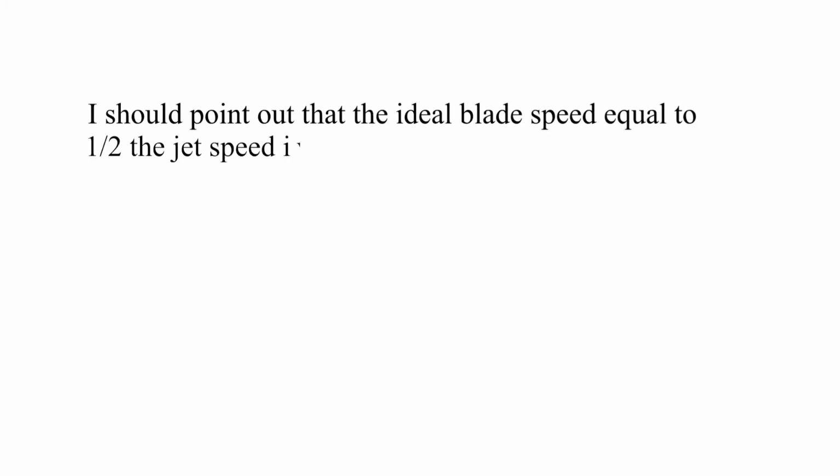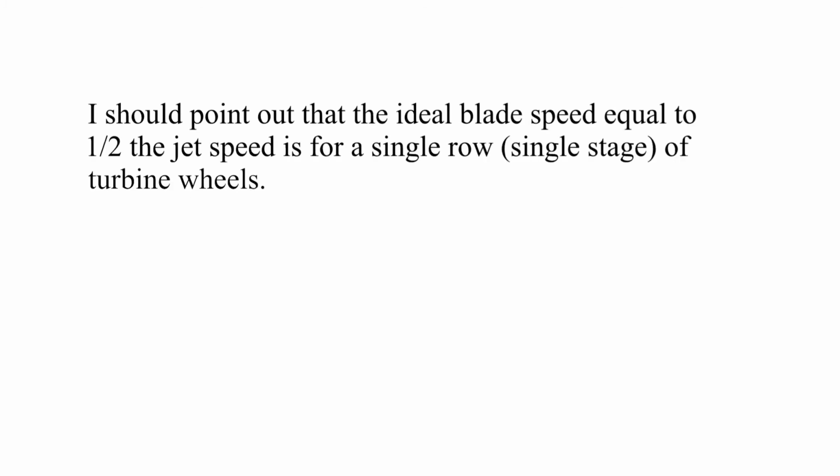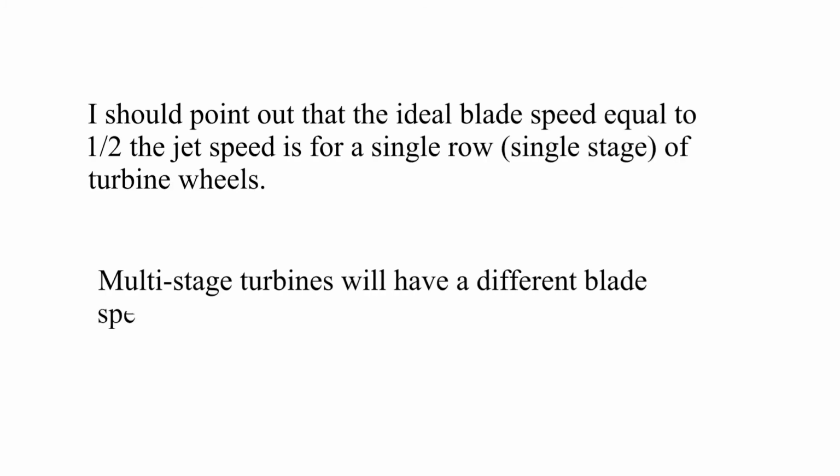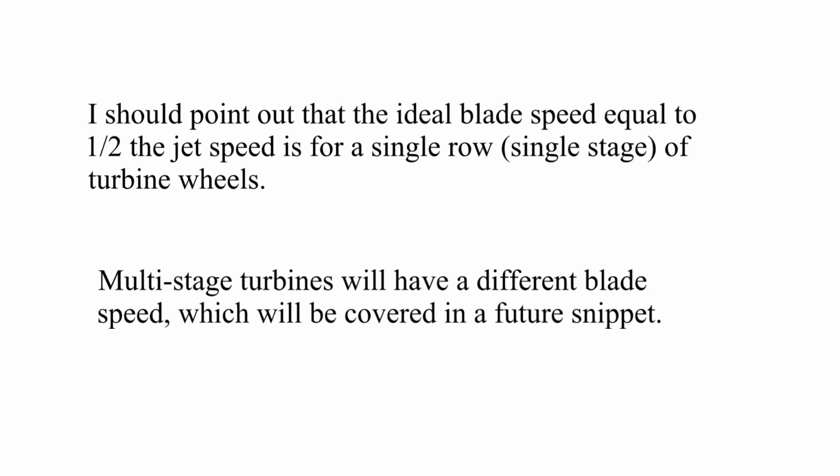The ideal blade speed equal to 1/2 the jet velocity is true for a single stage turbine. How to determine it for a multi-stage turbine will be the topic for another instructional snippet.